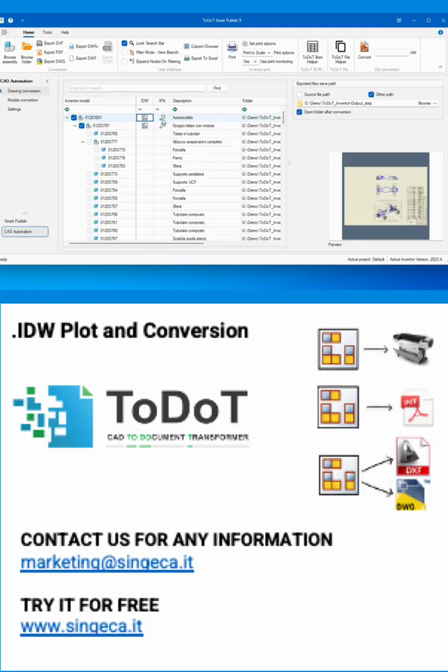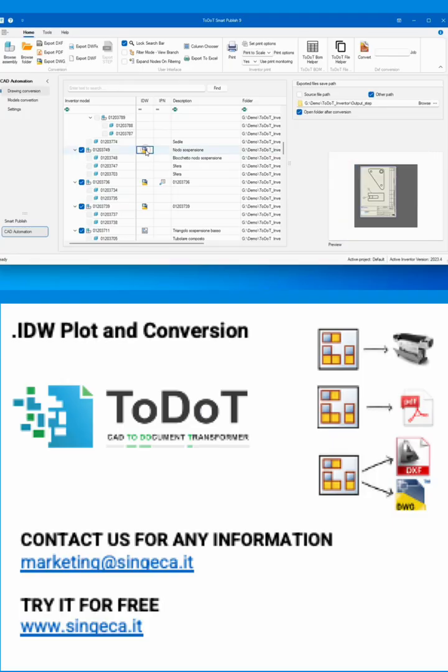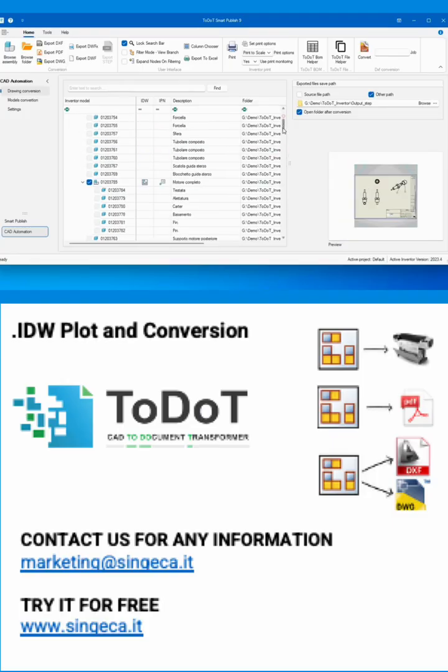By selecting a node, we can see the preview of the 3D model. If a drawing is available, we can preview the current sheet, and by clicking on the exploded view icon, we can see its preview as well. Drawings can be in IDW format or Inventor DWG format, and in the latter case, a specific icon is displayed. The tree structure shown here is the same as in Autodesk Inventor.